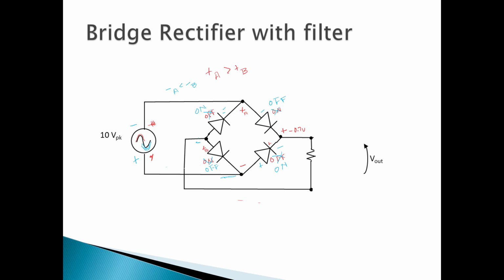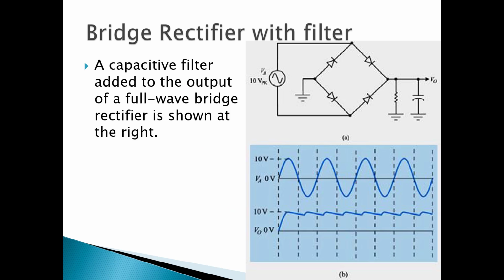And we will end up creating a waveform. All it did was convert the sine wave into all positive peaks. Right? So those bottom ones all got flipped up. And now when we put the capacitor on, that's there to smooth things out, and we end up with this kind of picture.